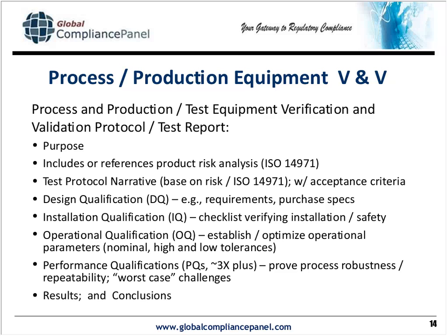You have to have the floor prepared for the weight and vibration and leveled, etc. You have to make sure that it has grounding, that it has the right phase and voltage of electricity and amperage, that there are safety issues. Although the FDA is less concerned with safety, certainly you've got OSHA issues, and why not include that as part of your installation qualification? I usually include light curtain issues or sensors as part of that IQ.